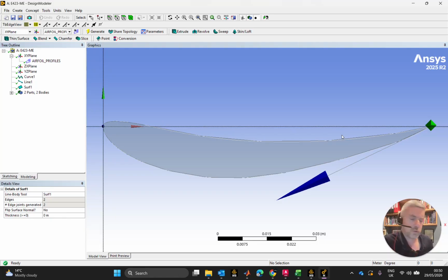So if my wing is too small, I'm not going to generate the levels of downforce that I want. And the other thing is I want to generate these levels of downforce at a relatively low velocity. I'm not a 747 here, number one. In fact, I'm not even a Formula One car here. In fact, I'm not even a STEM racing car here, where I'm looking to generate this downforce. Yes, this car will move fast, but it's not when the car is moving fast that I want downforce. It's when the car is moving at low to medium speeds, because it's on those low to medium speed corners that I want to keep the car pinned onto the road. So any downforce I am looking to achieve, I am designing for these corners, not for the straights.